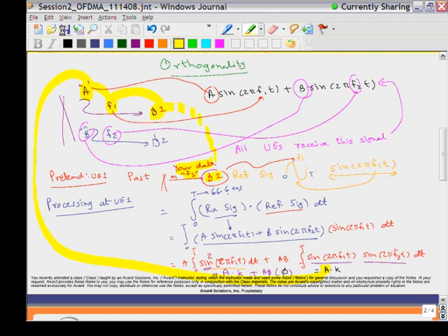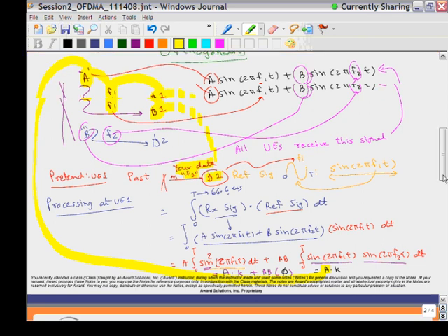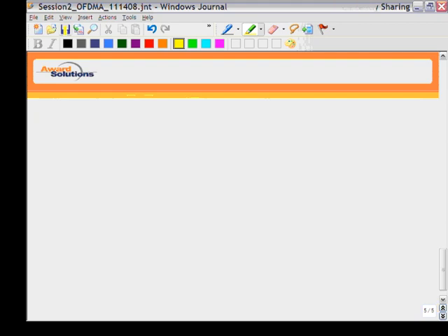So in summary, as shown by this mathematical processing, we have orthogonality among the subcarriers, because when you multiply your reference signal and the received signal and do integration, you will be able to recover your information, and with every other subcarrier, when you multiply and integrate by your reference signal, it will always give you 0. So this is how we can show that the carriers are orthogonal and we do not need to worry about interference. Okay, some other questions, we will take care of those now.